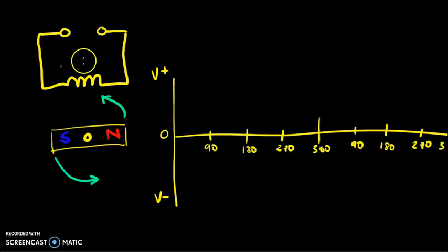This circuit diagram shows a simple generator which consists of a permanent magnet being rotated in respect of a coil. At this stage, the magnet is flat. There is no magnetic field, no lines of flux crossing the coil.